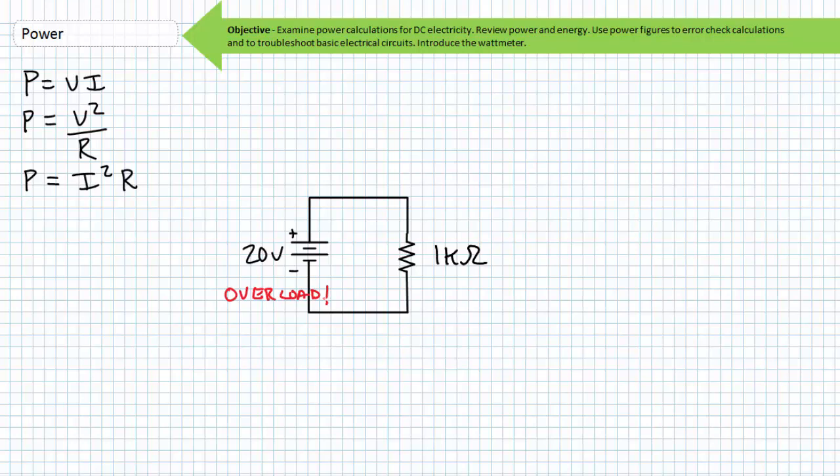Most power supplies are current limited, meaning there's a certain maximum current it will output, beyond which current just flatlines at a preset value. If your circuit draws in excess of this level, the power supply just says overload and refuses to supply additional current. This is a good thing and has saved many basic electronics students a swift boot in the backside for setting their lab station on fire.